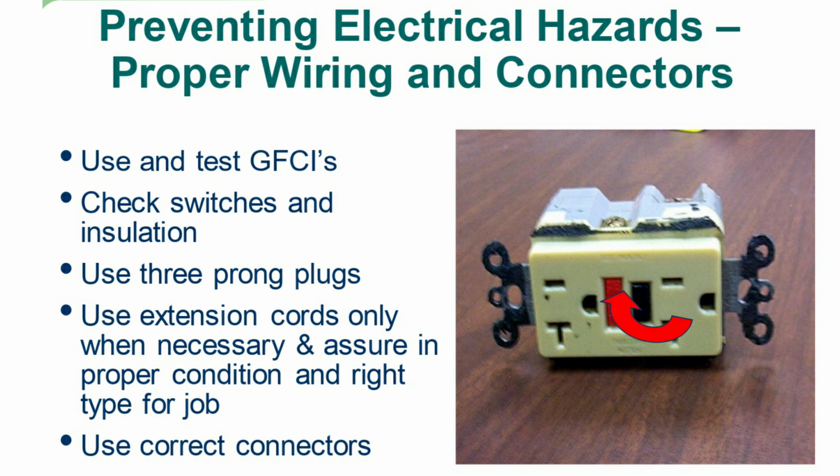Preventing electrical hazards, proper wiring and connectors: use and test GFCIs, check switches and insulation, use 3-prong plugs, use extension cords only when necessary, assure they are in proper condition and the right type for the job, and use correct connectors.